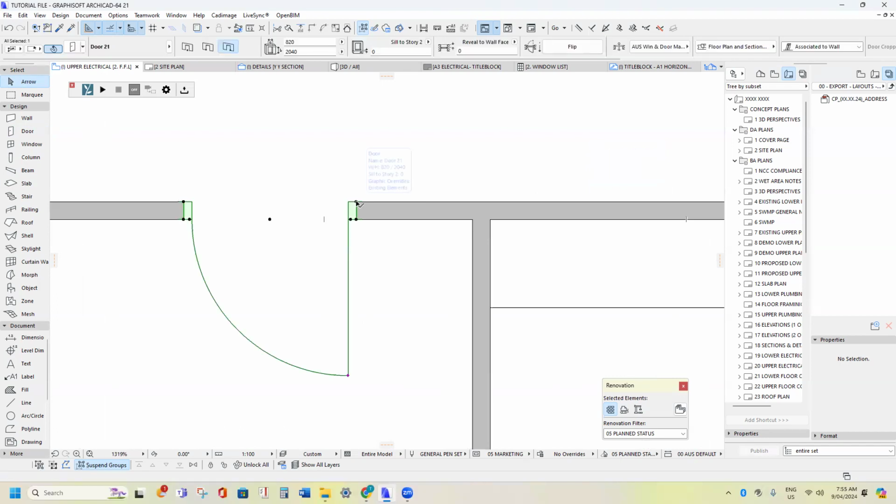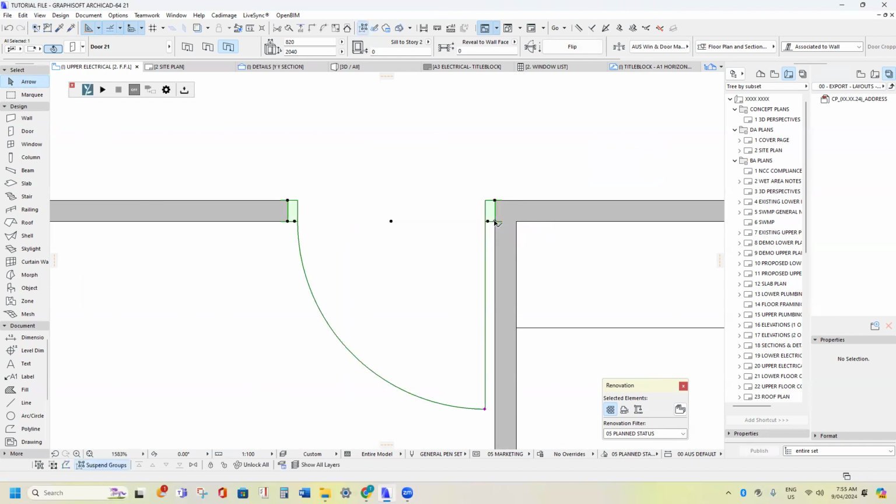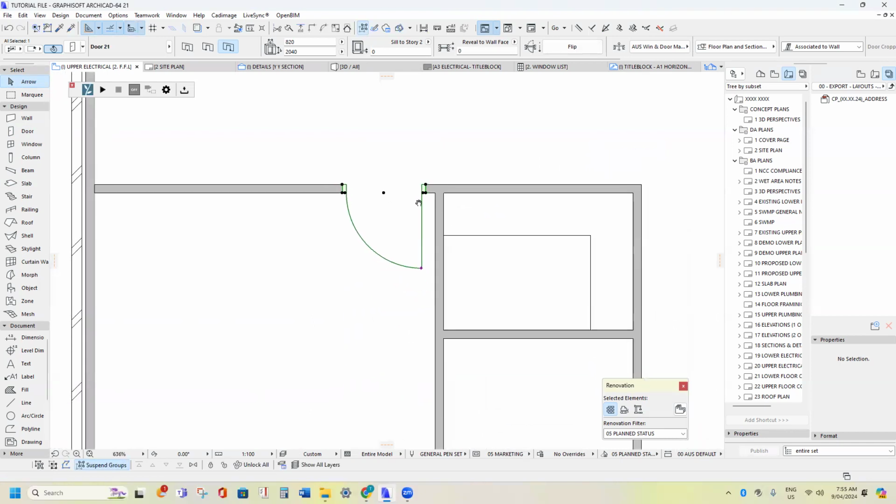So if I zoom in, click on the corner there, and then press Control D, click on that black dot where the tick is. Then come back to the walls here. There's a tick there again. It means I'm right on the corner. Click, press Control D, click again and move it off and press R 100. So I've got that door 100 mil off the wall.